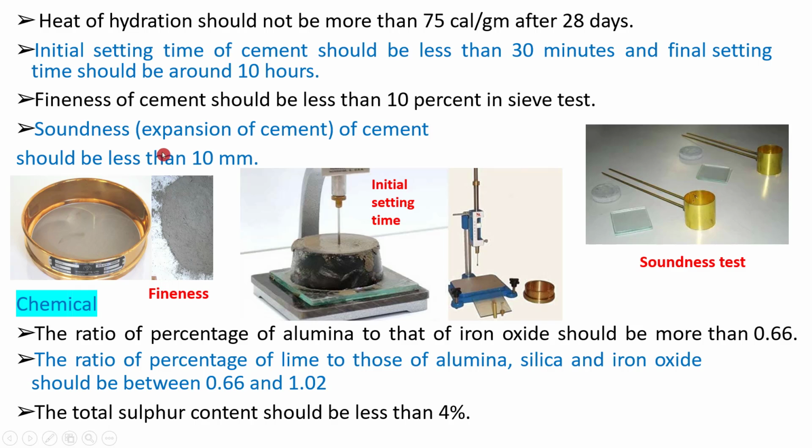And the soundness test. Here we have the soundness testing apparatus, and we will fill in the cement mortar, that means cement plus sand plus water, we will make a cement mortar and fill it into this one, and we will keep it idle for say 1 day.